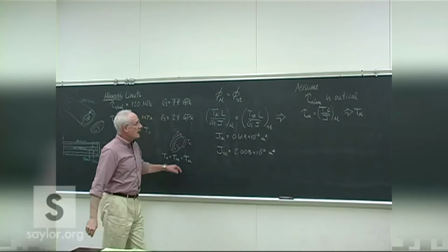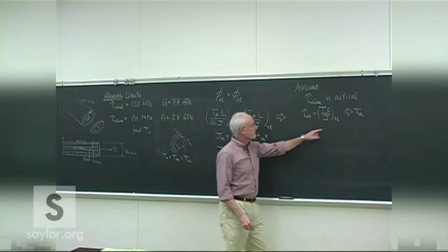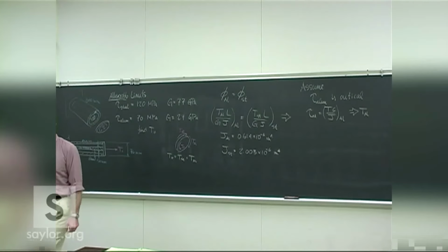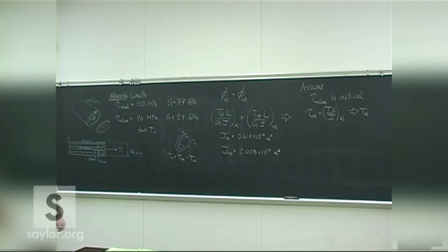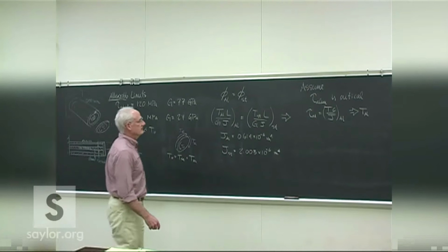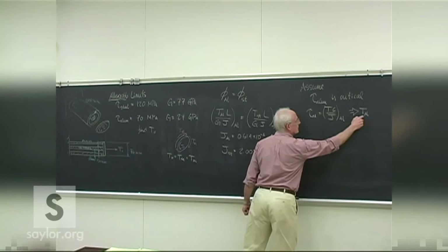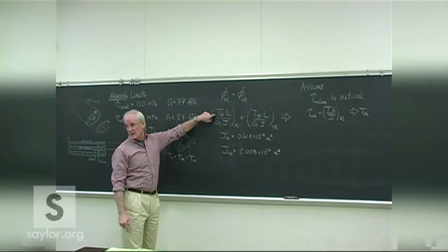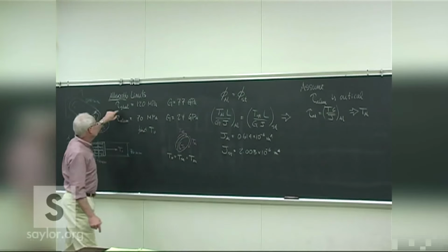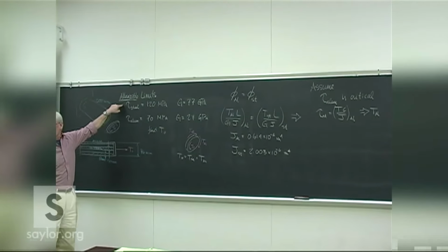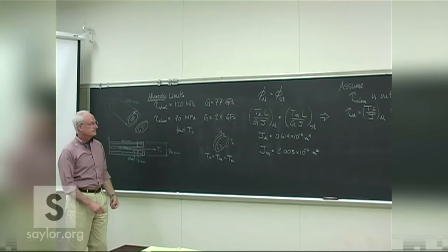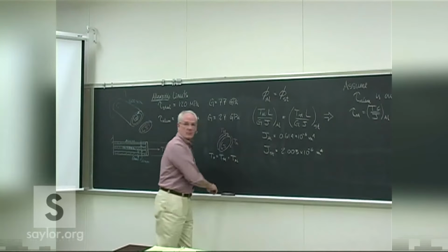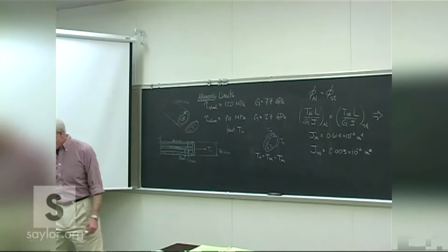We can then go back and test if we're at the limit on the steel as well. So once we find the aluminum torsion, we can then find the steel torsion that goes with that. We can then check to see if that's at the limit of the steel as well. So there's the bare bones plan.